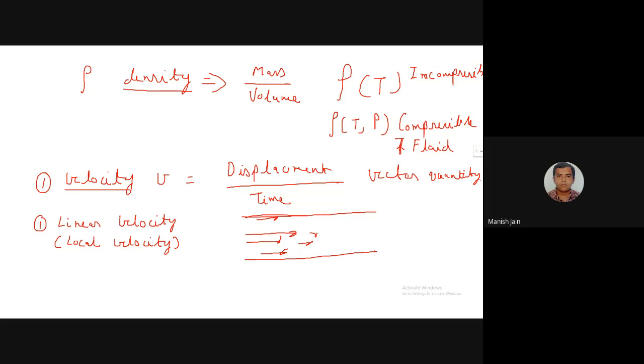At the solid liquid interface, where you have the pipe and liquid boundary, you have a friction force. The solid surface exerts friction on the fluid. That's why the velocity at this point is zero. At the solid liquid interface, the velocity of the fluid is zero. At the middle of the pipeline, you have the highest velocity, Vmax.